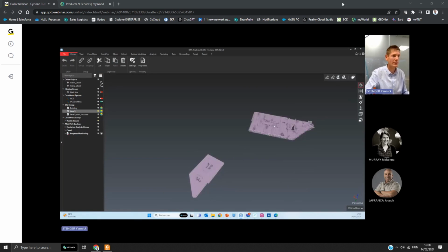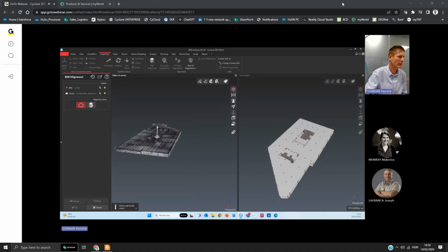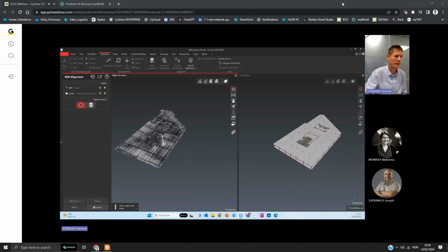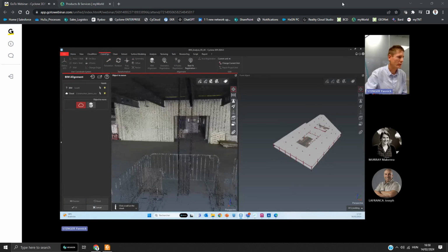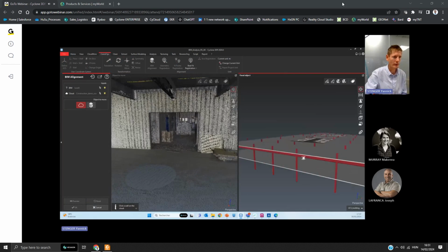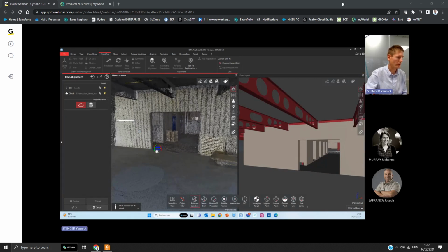So imagine that your design and your point cloud are not aligned together, which I believe is the case in 50% of situations. In the coordinate system menu, I'm selecting two objects, and I jump into beam alignment. This is a feature I probably demonstrated last time, and I think it's a very important one, and easy to use. I just need to position my two environments in the same view. And now I will move the point cloud onto my design model.